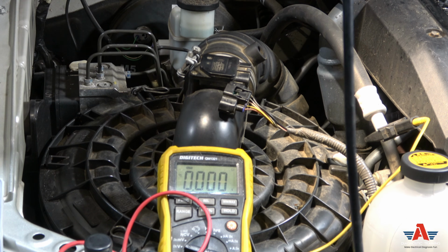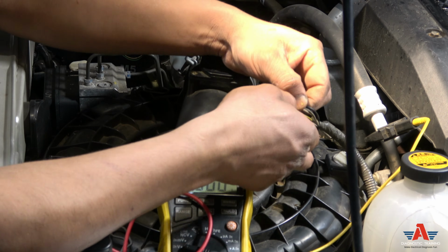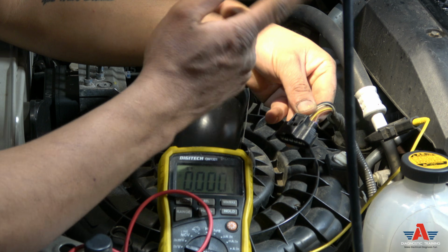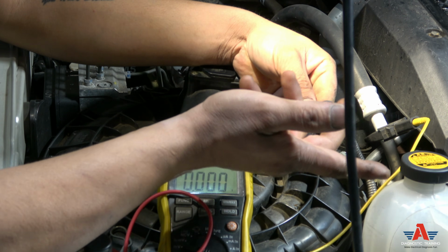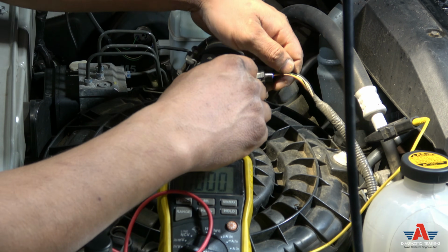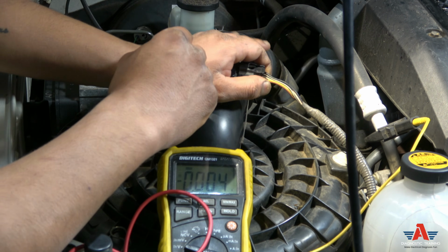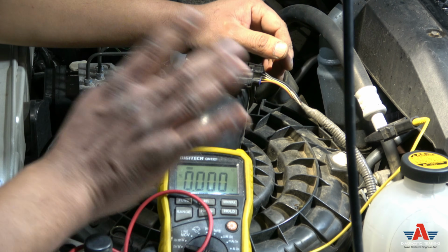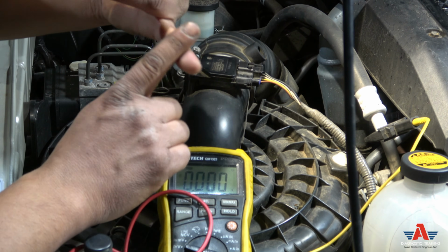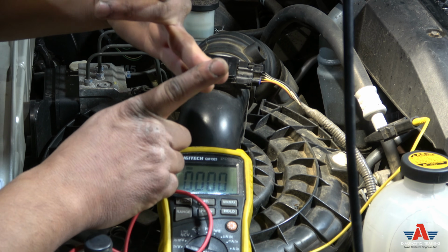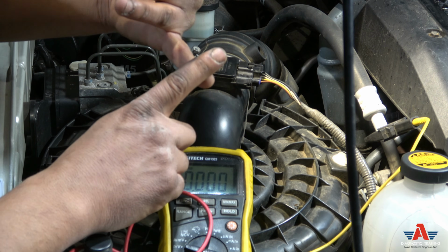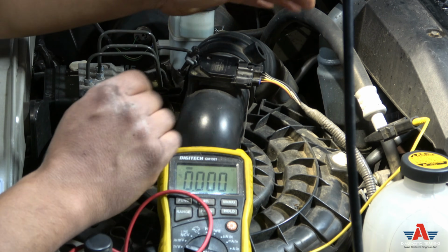Now, when you don't have a wiring diagram, as soon as you unplug it, let's say this is a coolant temperature sensor, you don't know which wire is what, just put your test light or multimeter on it, and you'll know which one's the 5-volt circuit wire and which one's earth. Okay, that's pretty simple. All right, guys, saying that, just treat any temperature sensor like this. Anything, doesn't matter what it is reading. Doesn't matter if it's oil temperature, coolant temperature, fuel temperature, air temperature, cabin temperature, outside air temperature, it's all the same.